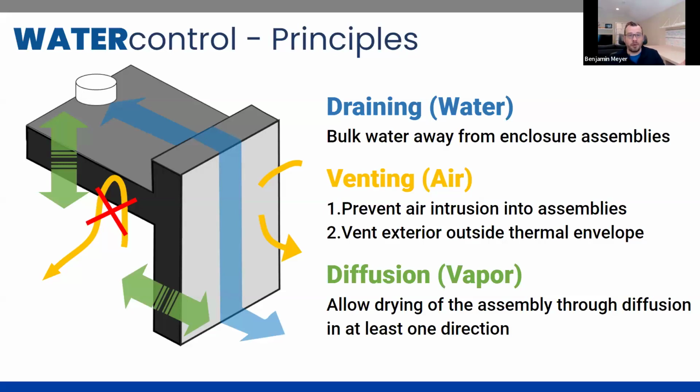Those are important to understand. And then also, as you get to where the building meets the ground, the ground drains away. If you can get the benefit of venting or allowing any moisture that gets behind a cladding to dry back out, that's going to prevent or limit the amount of load you have to deal with if there is a leak. So some of that is really just a matter of risk management.